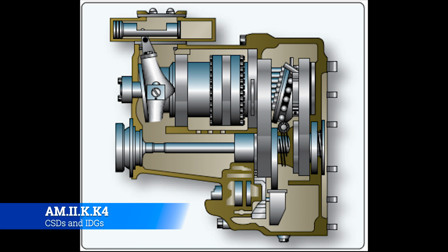But then as you really start to get going, you realize we really need to be cruising. We don't need this much power, so you go to third gear. That allows you to leverage the amount of power the engine is producing, which is lowered significantly from when it first took off, but still maintain the speed the car has been moving. And then it keeps on going up, fourth, fifth, sixth gear, and that allows you to economize the engine as much as possible. You don't need to be at 7,000 RPM to be going 70 miles an hour. You might be able to only do 1,900 RPM and maintain 70 miles an hour.